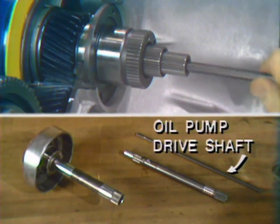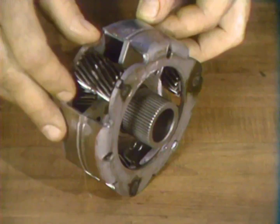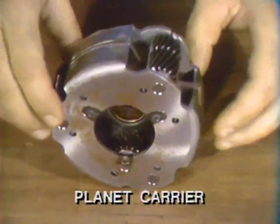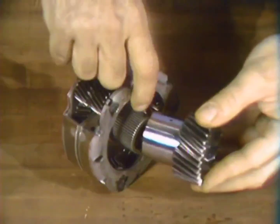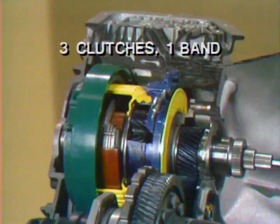This is the oil pump drive shaft, and it turns inside the intermediate shaft. The main planetary gear set is a compound design similar to the FMX and the automatic overdrive. But here's the 4th difference. Its output is always through these splines to the final drive input gear. And 5th, the friction clutches and band functions are different because of the gear train arrangement.